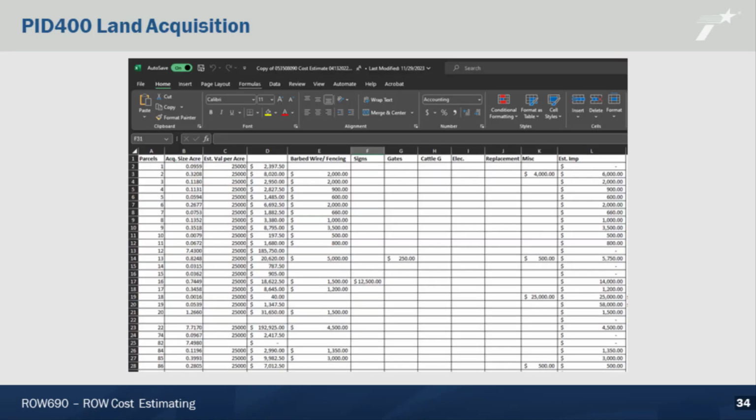Because a project is likely to have several types of parcels, vacant or developed, residential or commercial, you probably can't do a one-size-fits-all calculation for the land acquisition costs. You may have to do several different calculations before totaling up the acquisition costs on your project. You might find it useful to make a spreadsheet of the parcels on your project to help you do the estimate for the different parcels you have. Lots of right-of-way project coordinators and project managers have created spreadsheets for this purpose. Check with your colleagues to see if they have one that would work well for you.